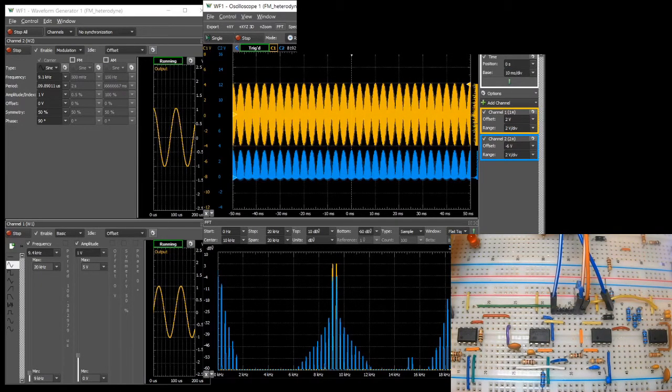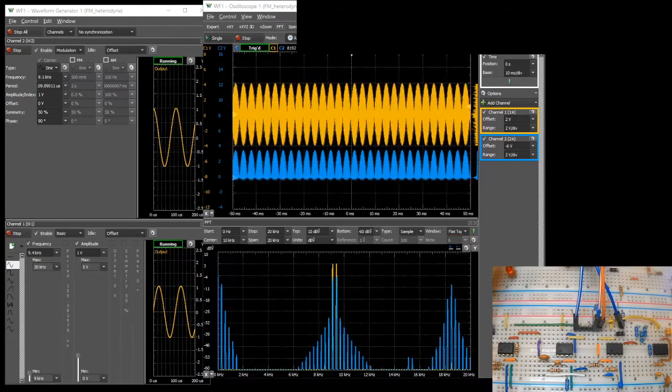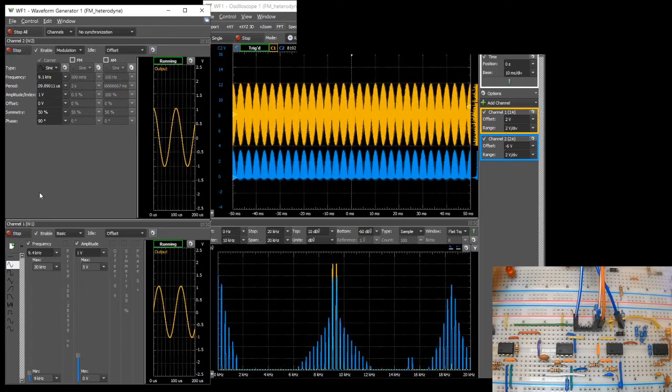It is evidenced by comparing the Fourier spectrum of the yellow trace, which is the beat signal before the diode, and the Fourier spectrum of the blue trace, the signal after the diode, that there are many nonlinear mixing components, and that the power of many are significant, within an order of magnitude of the main components.